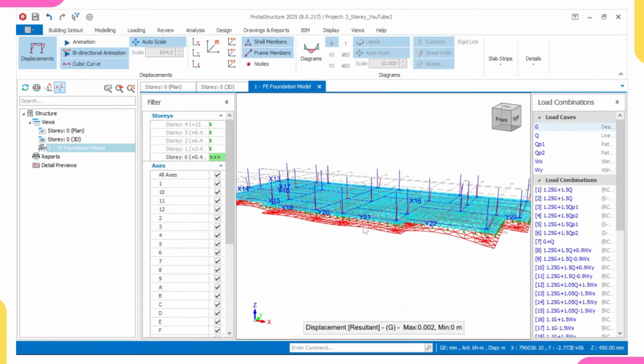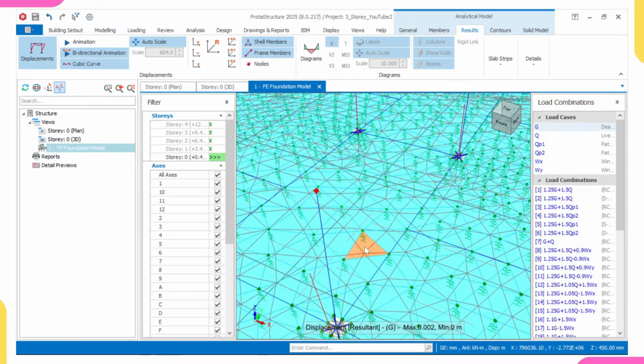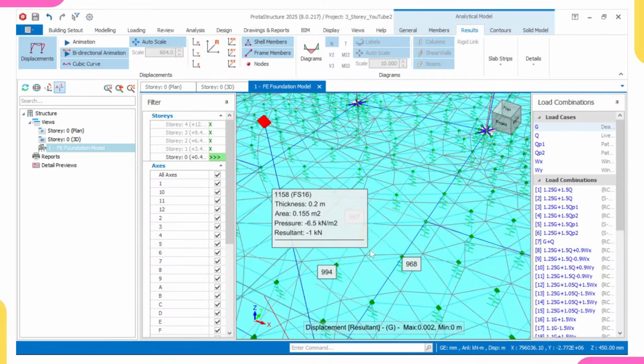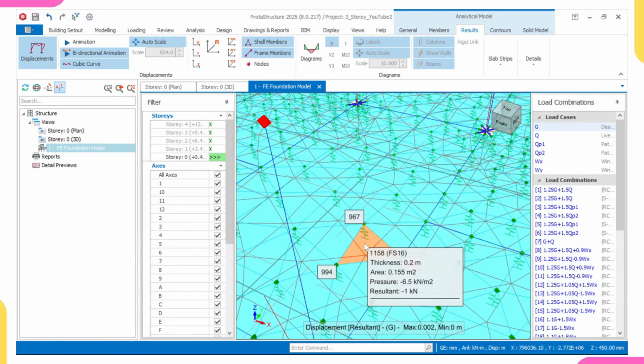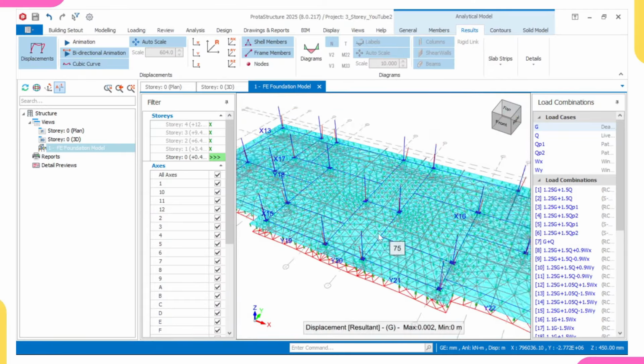So this is the analytical model. Look at what we mean by that shell element. If you see now, look at that 1000 and that 500 that I'm showing you. Assuming I choose any value less than 1000 or less than 500, this triangle will be smaller. This shell element will be smaller, which also means that the analysis will be more accurate, but I will just advise you to leave it at default. So this is what we are having.